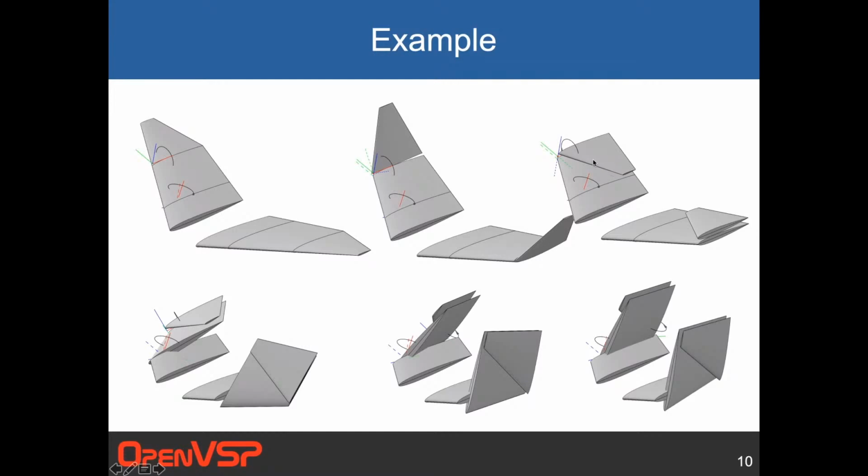And then this also has a Grumman fold. So this hinge axis is 45 degrees in and down at about the quarter chord in the center. And that causes this wing leading edge to fold down under until it's back parallel to the fuselage. And so this is a wing with two folds. First the tips fold, then the rest of the wing does a Grumman fold back along the body. I'll show you this demo in a minute.